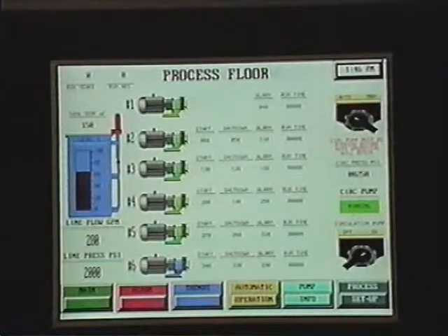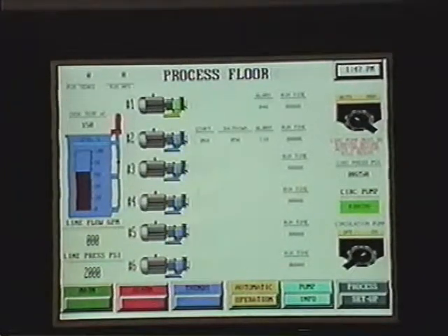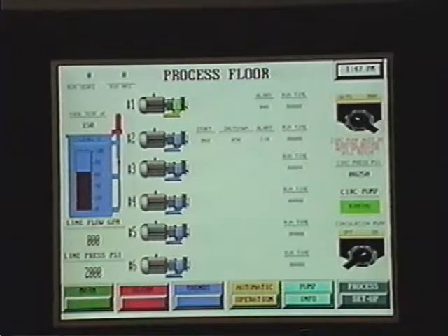So I'm going to shut down the pumps down to pump number 1, and then bring it up and cause number 2 to go into alarm, so you can see how that system works. If the demand on the floor goes to 0, the pumps will all turn off in a few seconds, and we're back to the original condition, which shows that pump number 2 will start at 60, shut down below 50, and will alarm if the flow is less than 110.